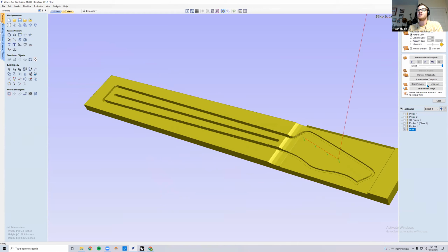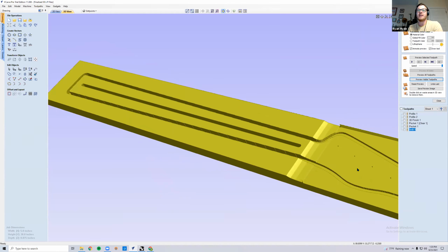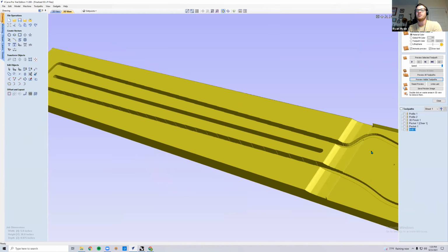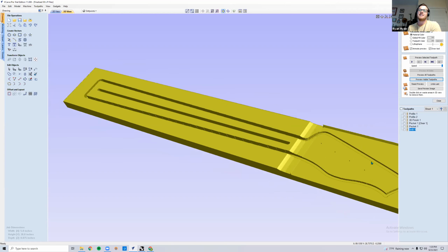And then I'm going to drill out some headstock holes. These are just little pins because what I actually want to do is take a custom drill bit later that's perfectly sized for the tuner holes at 9/16. So I just drill little dots with a 16th inch bit or a V-carve bit or something like that to mark the holes, because CNC isn't the best at doing this.